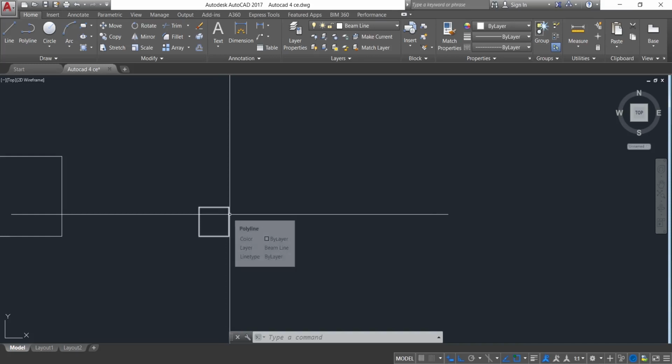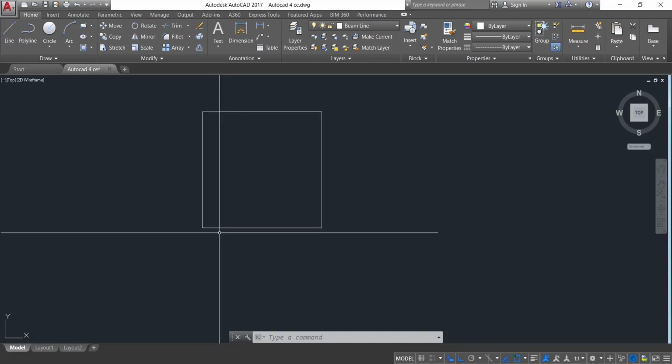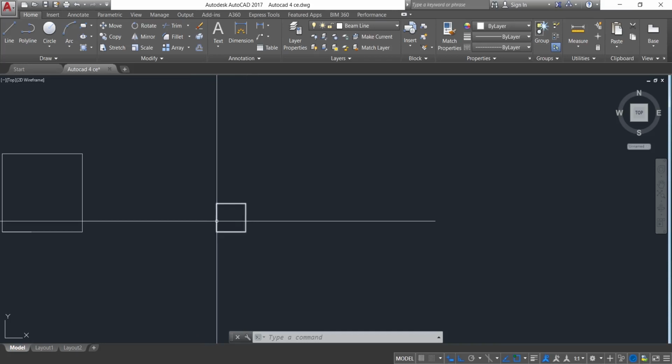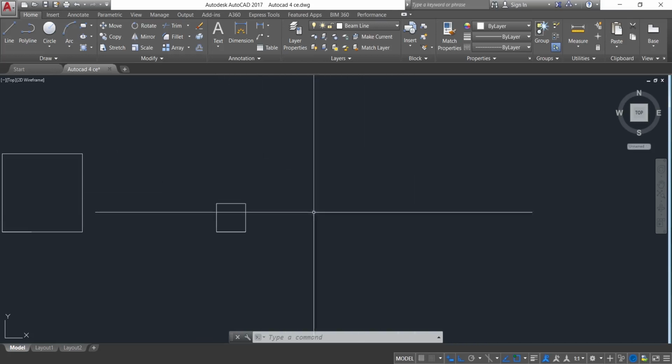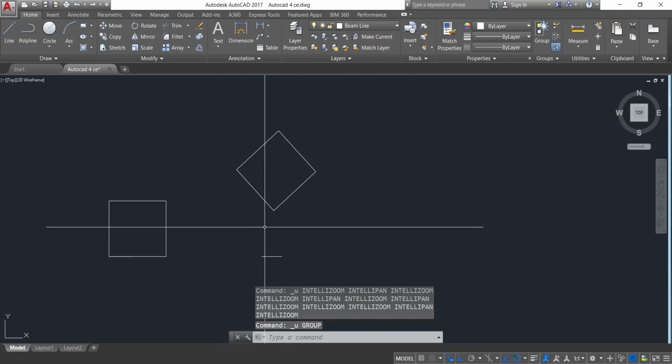What you just have to do is import the PDF into AutoCAD. Once you do that, you create a line of which you know the dimension. Then you align one part of the object that you are very sure of the dimension of with that line. I hope you can do that. That is the purpose of the align command. You can use the align command to align anything to another thing, as long as you are able to pick a minimum of two points from the source object and a minimum of two points from the destination object.